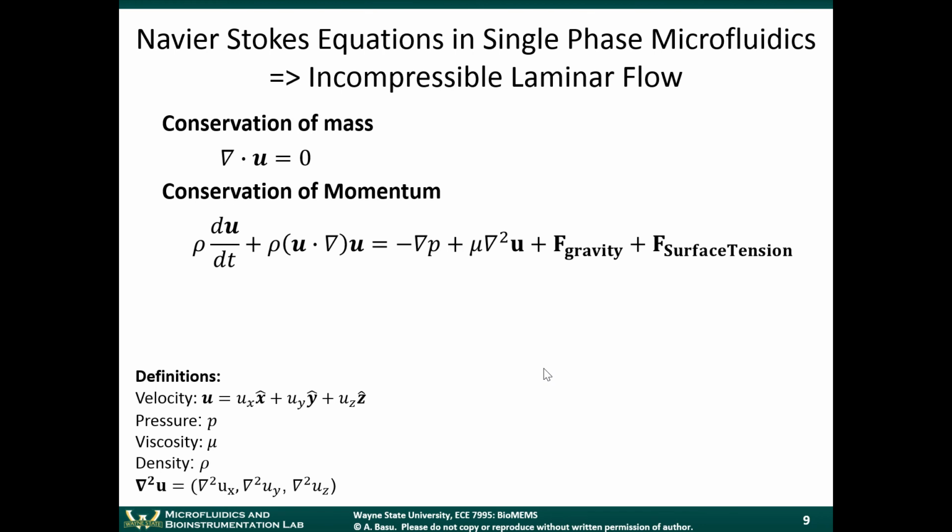All right, if we start from first principles, we want an equation that describes the flow of fluid through the channel. There's a conservation of mass, and then there's the conservation of momentum. The conservation of momentum is sometimes referred to as the Navier-Stokes equations. Sometimes they're both together referred to as the Navier-Stokes equations. But basically, it's a statement of conservation of mass. This is what's called the material derivative. It's set equal to 0. And then you have the, I'm sorry, this is the material derivative. This is just the divergence of the velocity. That's equal to 0, basically saying that mass can neither be created nor destroyed at any point.